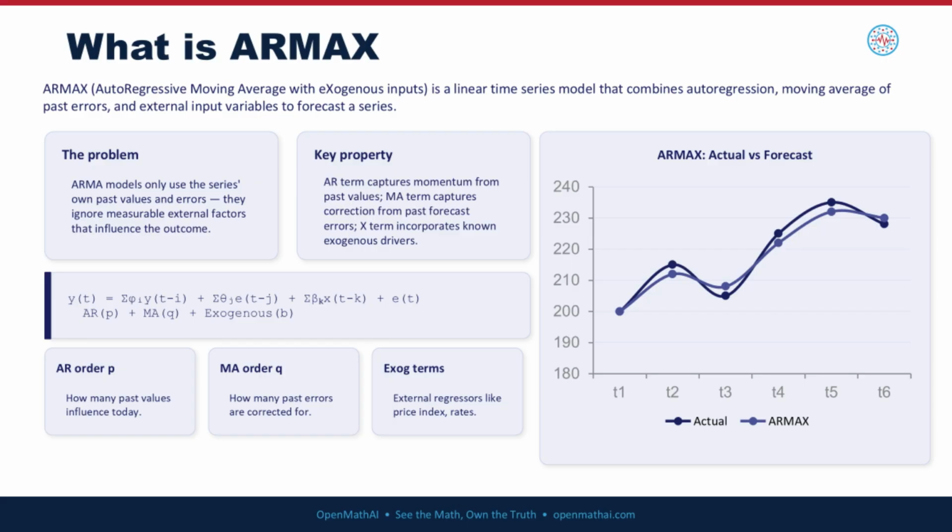to improve future predictions. During prediction, ARMAX combines the previous output values, delayed external inputs, and previous residual errors using the coefficients learned during training. This allows the model to represent both the dynamic behavior of the system and the effect of disturbances.